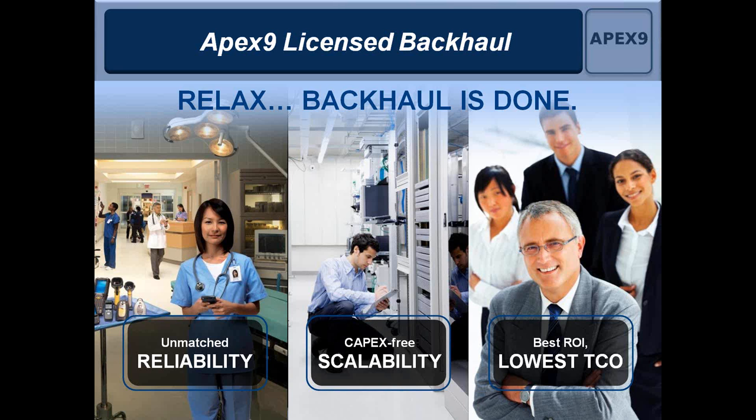you just go the safe course and go Category A and put up a 6-foot dish and call it a day. Now, there's a reality that a 6-foot dish is pretty large. They're also fairly expensive. I mean, they're at least probably double the cost of a 3-foot dish, I would think, if not more. And then there's that annoying thing of recurring tower rent. I'm not quite sure exactly how it might be in your market, but what I've experienced is the general rule of thumb is it's about $100 a month per antenna foot on the tower.